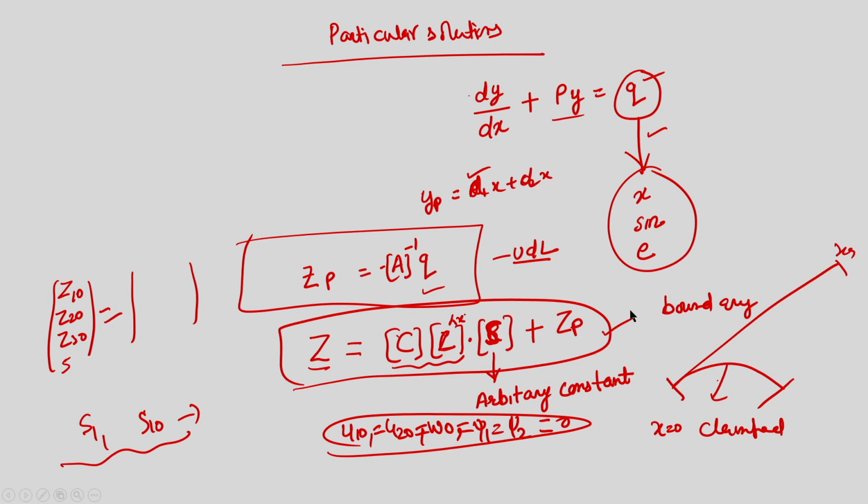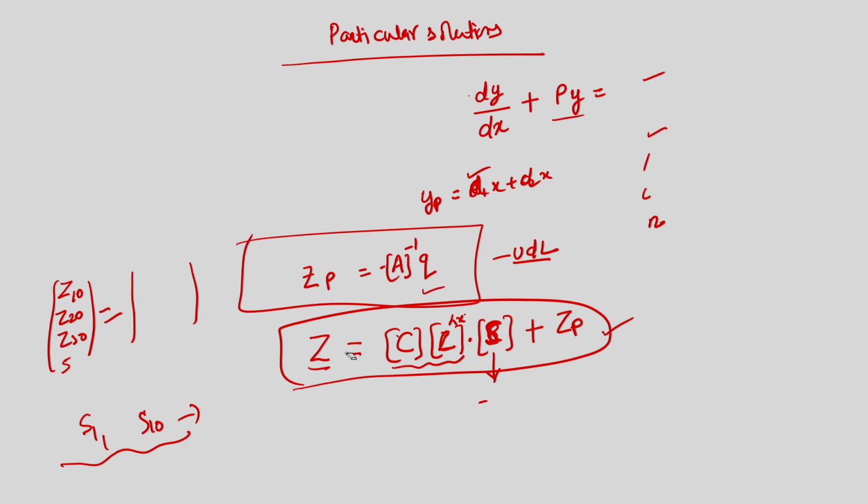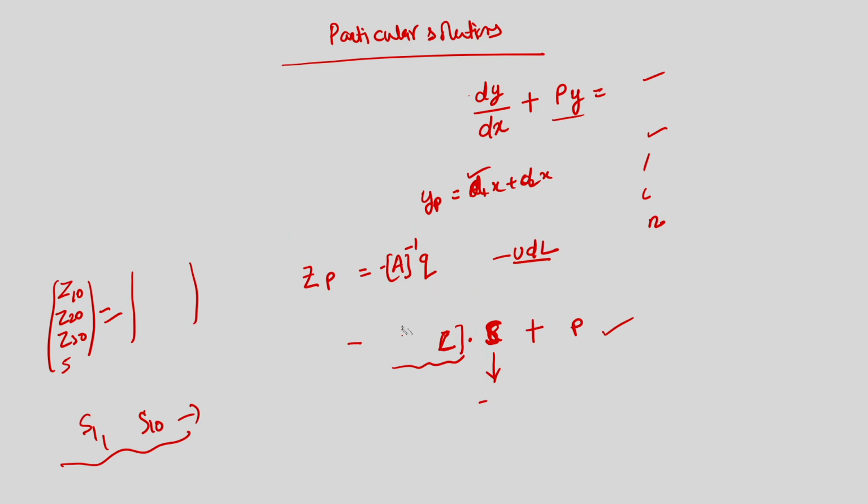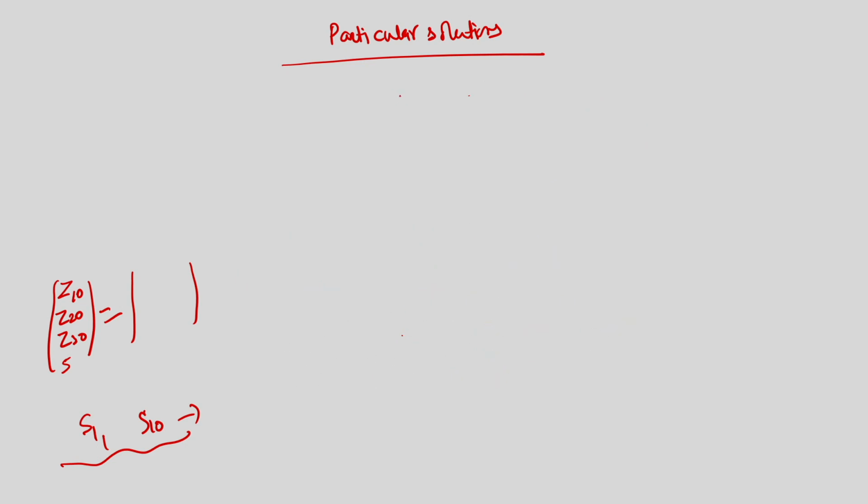So in this way the problem is solved for the case of a Levy solution when it is having a transverse load. For the case of free vibration, there will be no load. So in that case, Z comma x can be written as A into Z. There will be no loading, so it will be only a homogeneous solution.